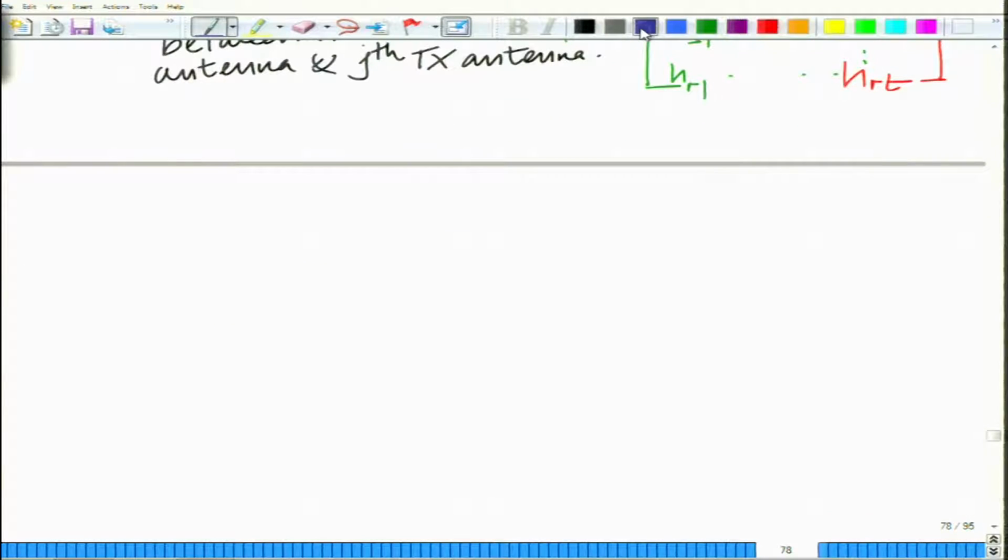And now the key to understanding this decomposition of the MIMO channel into a set of parallel channels is what is known as the singular value decomposition. We will use this technique, which we have probably briefly referred to once earlier in the context of optimal beamforming. We will use this construct and subsequently demonstrate optimal power allocation for this MIMO, that is, multiple input multiple output wireless channel.